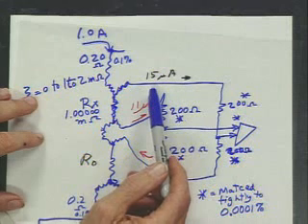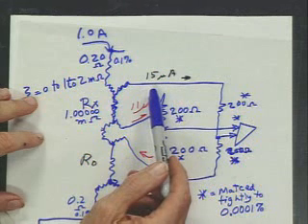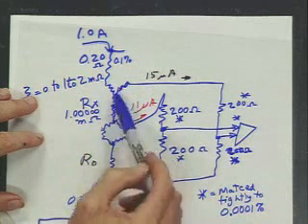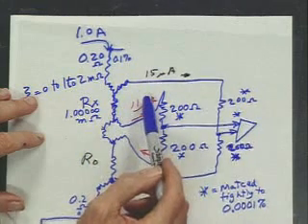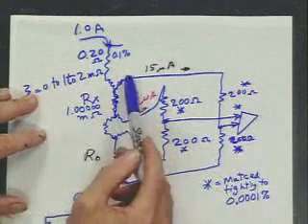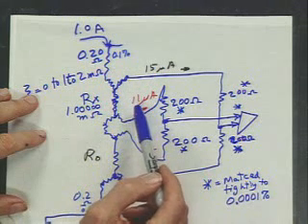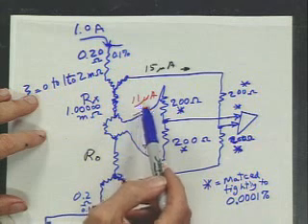Not a big signal at all. Well, 45 nanovolts is 45 parts per million of the 1 millivolt signal, which means, if we can't avoid this 45 nanovolt signal, we're in trouble. We're going to lose all our accuracy.